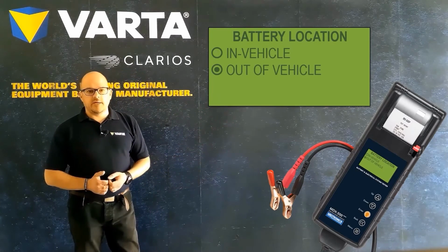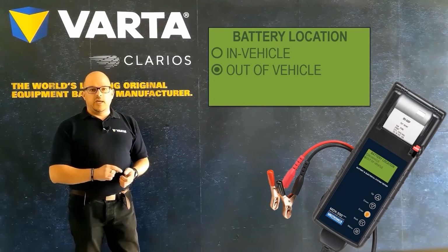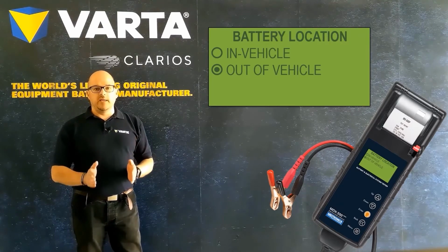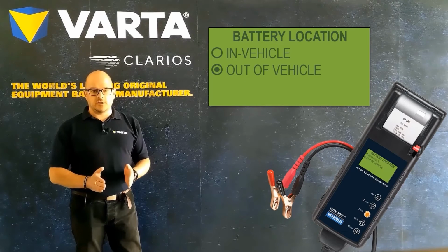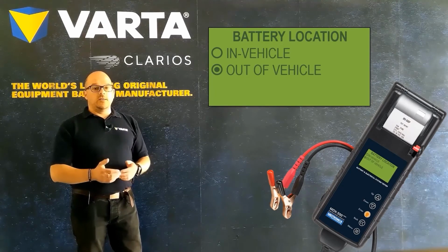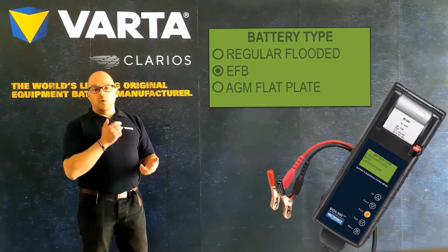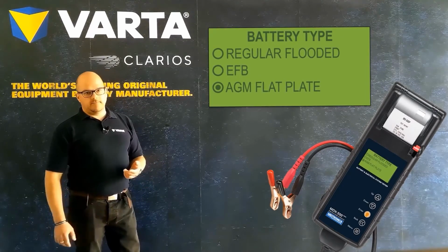Next, select the battery type. Something to note here, when a start-stop test is selected, it will only display the battery technology relevant to start-stop vehicles. Otherwise, you could select a regular flooded battery, an EFB, or an AGM flat plate.